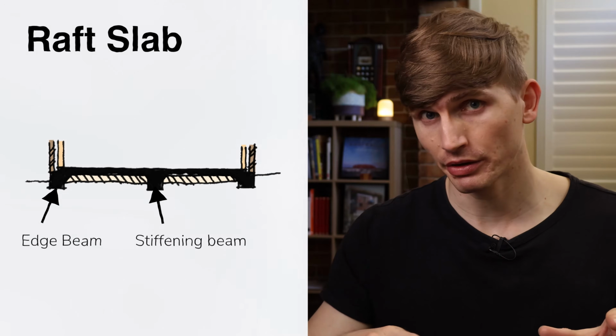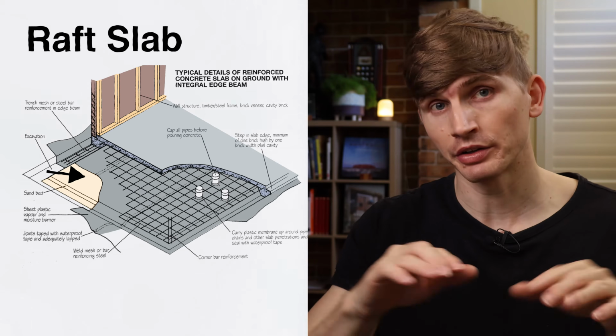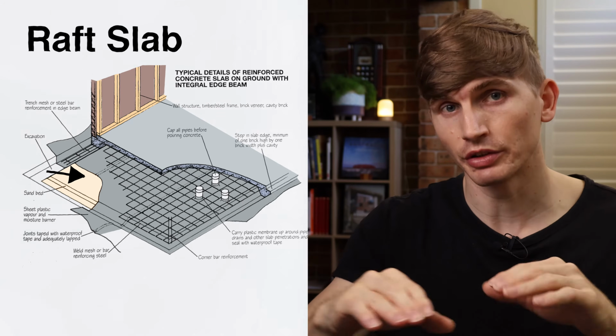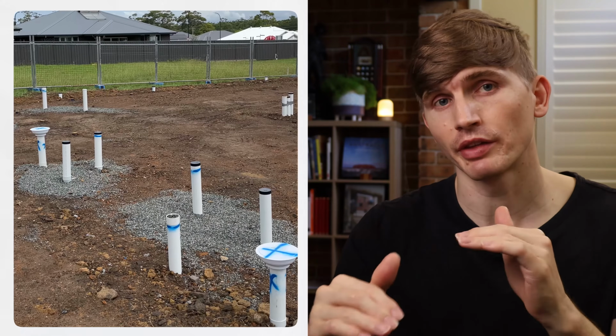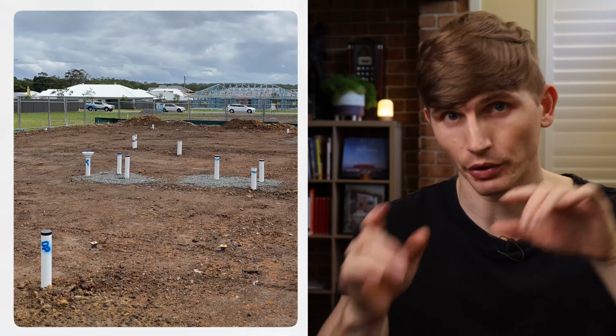Now, after excavation, the edge beam and any stiffening beam areas should also be excavated to adequate weight-bearing foundation. The area underneath the slab is then filled with fine aggregate or sand, which is then leveled and consolidated. Next up, any drains that need to be placed underneath the floor need to be placed, being particularly careful to get them into their correct locations, because with this, there's no second chance.